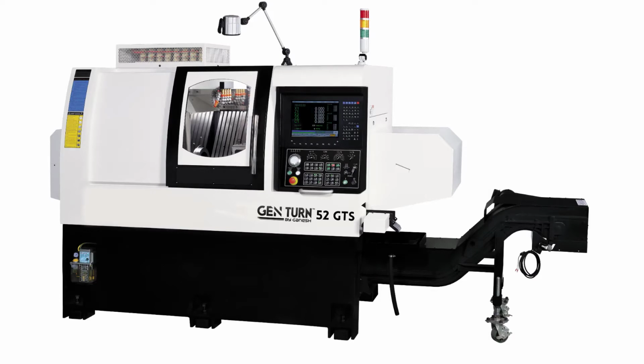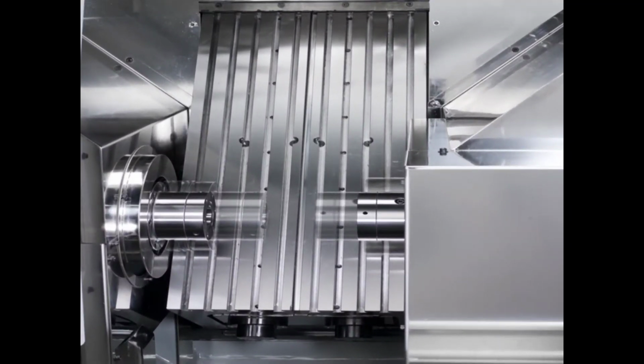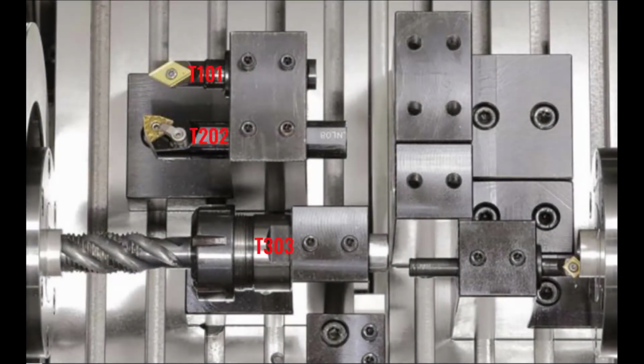This video explains taking the offsets on the GENTURN 52GTS dual slide gang tool turning center. A gang tool machine allows you to place a tool holder anywhere on the slide. The slide has a series of T-slots to accept the tool holder. The tool numbers are dependent on the tool offset value that tells the control the position of the tools on the slide. You can place any number on any tool just by setting the tool offset value to the tool location on the slide.